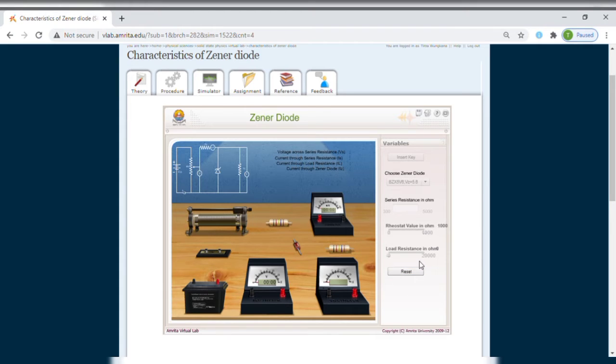So after that, we're going to connect all of these. To make a connection in this simulation, click one end node of the battery and drag it into the next position where we want to connect the wire, just like shown in the figures below.